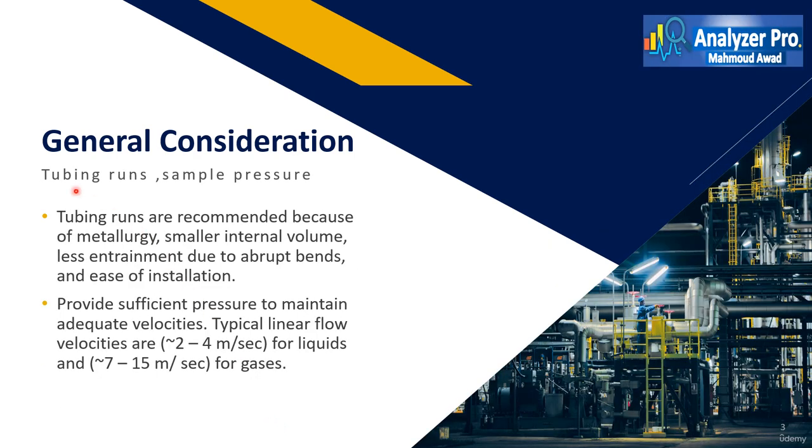Next, we will talk about tubing runs and sample pressure. Tubing runs of seamless tubes are recommended for many reasons, such as their metallurgical properties, the smaller internal volume, less entrainment due to abrupt bends, and finally ease of installation. Another important consideration is that we have to provide sufficient pressure to maintain adequate velocities. Typical linear flow velocities are from 2 to 4 meters per second for liquids and 7 to 15 meters per second for gases.